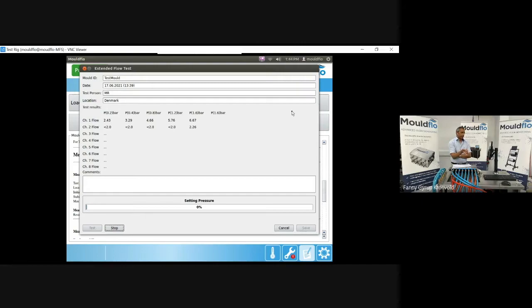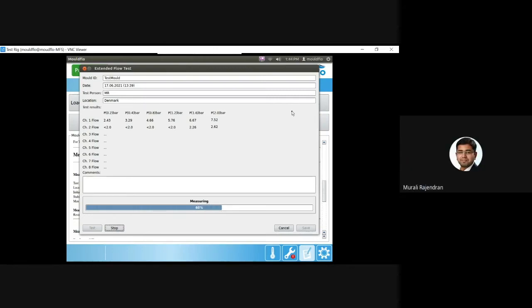In this mold that we are testing, it has 4 cooling channels, and all of the cooling channels are the same size in diameter. So we can see that in cooling channel number 2, obviously there is some kind of problem. There is a blockage or something, and that needs further investigation. If all these channels are the same size, then there's definitely an issue with that.